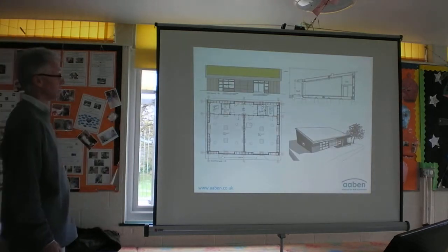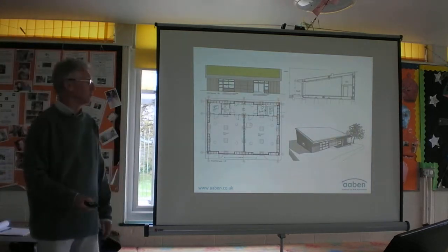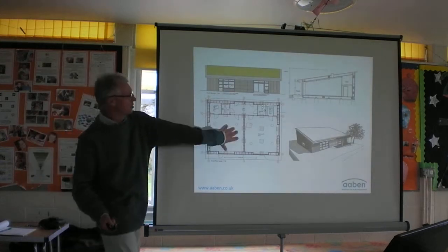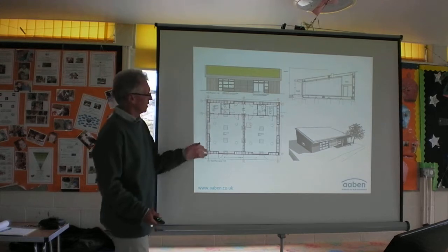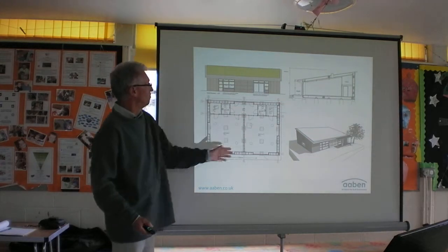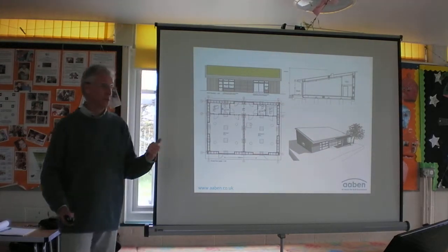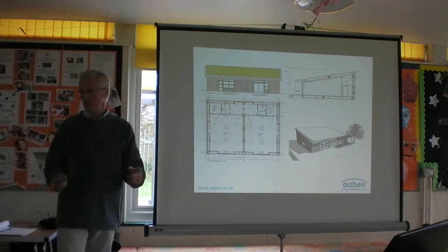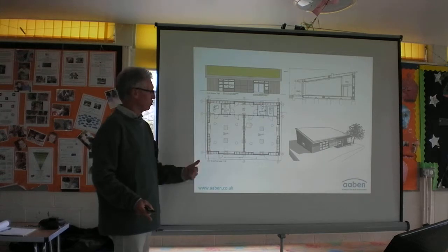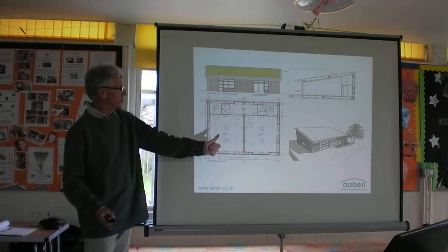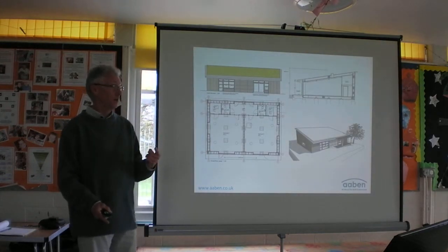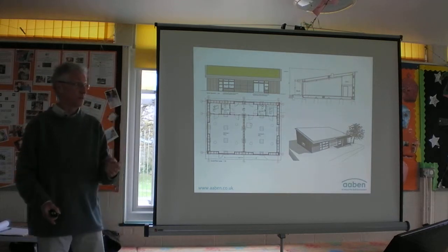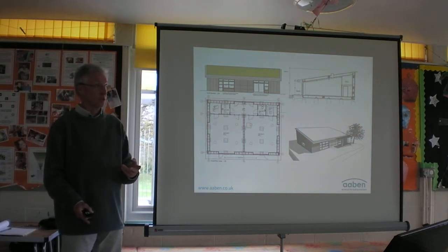This is something we've designed. This is where we started 3 years ago with the school buildings, and we wanted to design a classroom. And we came up with this 2-classroom unit. It's roughly square in form, but it's still single story, which is difficult with Passivhaus. We do that with a 400 I-beam, 500 wall completed, but it will achieve Passivhaus standard, even with school high occupancy, high ventilation issues, high humidity issues.